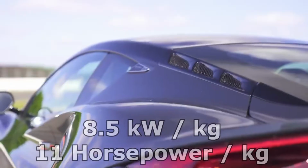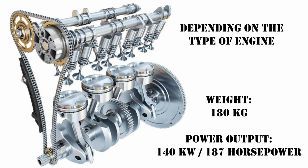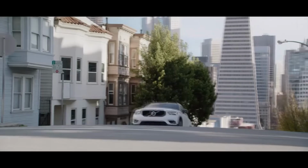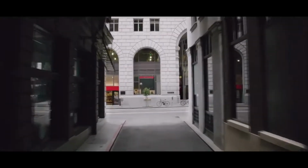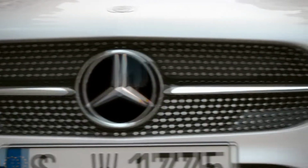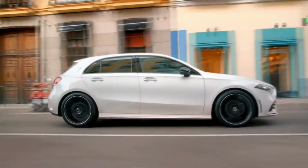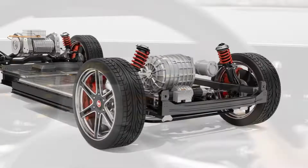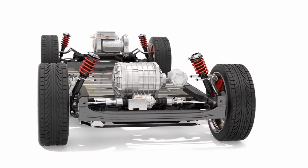An engine can weigh up to 180 kilograms, with a power output of 140 kilowatts, or 187 horsepower. However, this depends on which type of engine it is, whether it is twin-turboed, supercharged, or even a bigger engine. However, 187 horsepower is roughly the same horsepower available in a Mercedes-Benz A-Class, making the power-to-weight ratio 0.78 kilowatts, or 1.04 horsepower per kilogram. The induction motor receives power from a large battery pack.